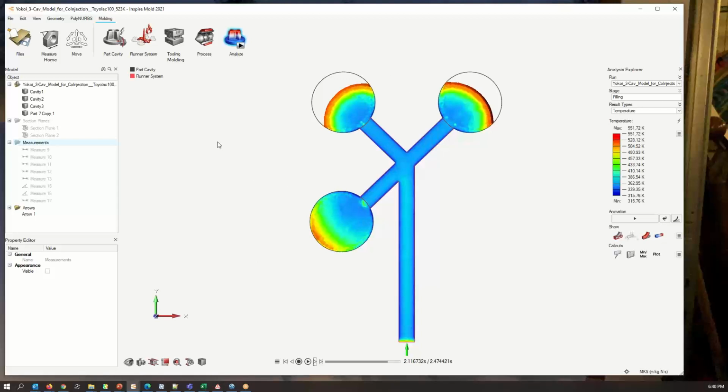You can get just a simple plaque. You go to mold it out of a polycarbonate or an ABS, and you'll see what's called a race tracking effect down the edges of the part because of a fan gate that's in it, and you'll see that the flow front turns from convex to concave as it fills. That's a pretty significant effect when you talk about shear thinning and odd shear behaviors in a polymer melt like this. So this is an important effect to understand, and to know when you're seeing something weird that doesn't seem to make sense, maybe this has a little bit to do with it. It's good to understand these things.